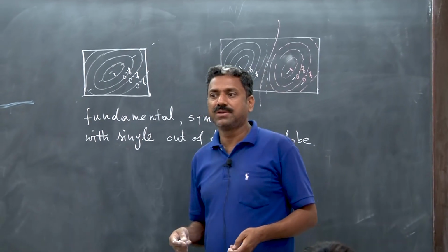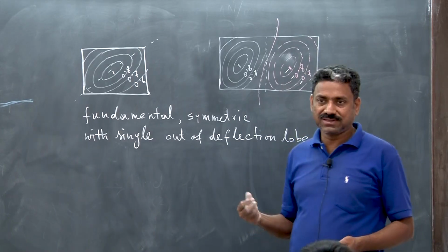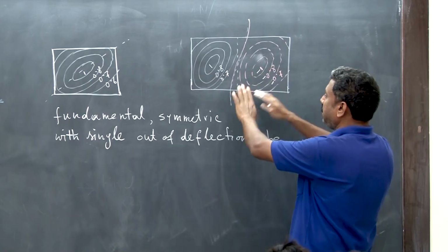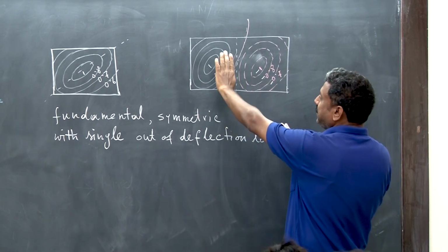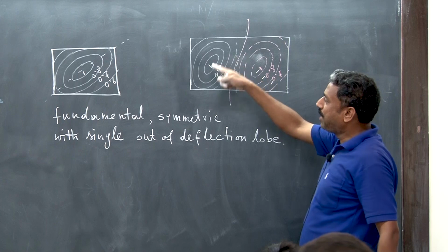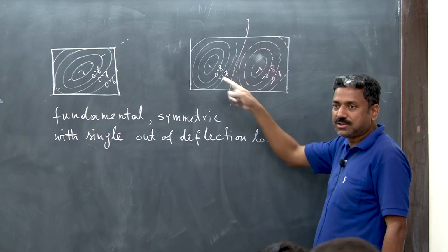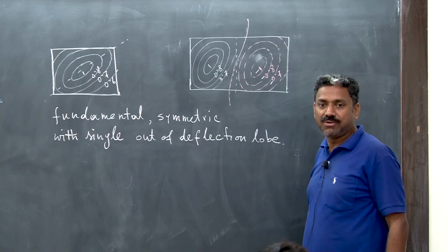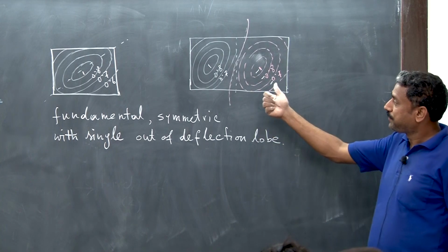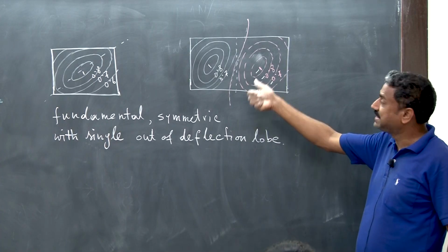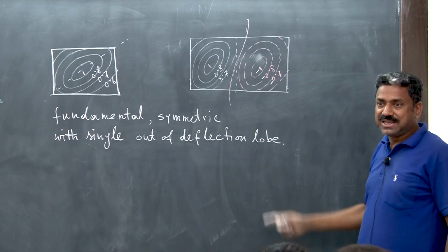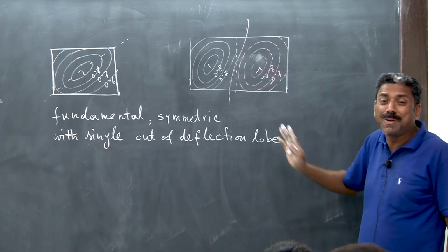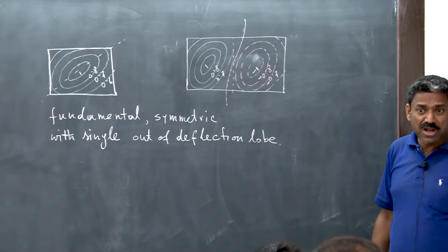When you solve the Poisson's equation, you will get the warping functions, and then from there you will plot. You have plotted that. So here the aspect ratio is around 2. This fellow is going up, this fellow is going down. Once again, this little oblate shape is because of the tensile stiffening along the other diagonal direction. Similarly, this is the second mode, and this is an antisymmetric mode. This is positive, this is negative, right? And it is having 2 buckling lobes, right?